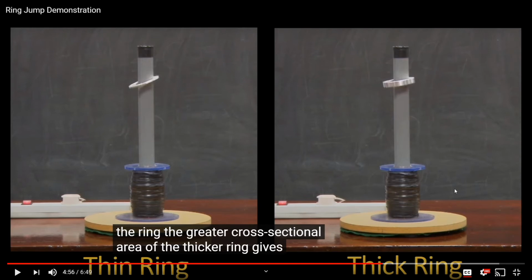If the resistance is lower, the current goes up, right? Given the same EMF. And they're both experiencing exactly the same EMF, remember that. Because the EMF at that point is related to the number of turns times the time rate of change of the magnetic flux. They're both the same size, so they're the same area. They're both experiencing the same rate of change of magnetic flux because they're both being affected by the sinusoidal power source, right?